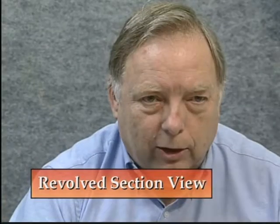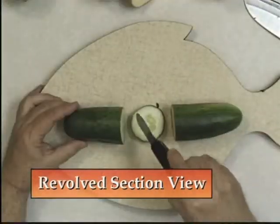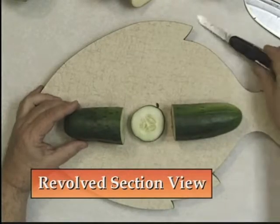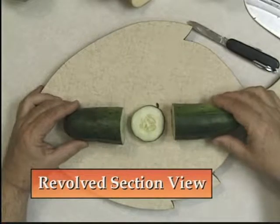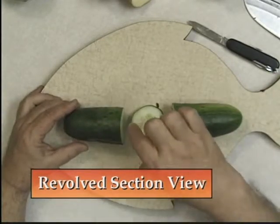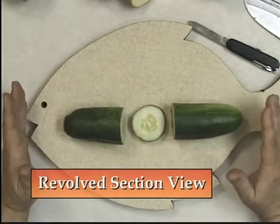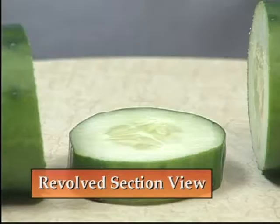You'll see later when we get to the formal views that we actually leave a little space or a little break in the view for the sectioned part. So here we have this long object and we want to show the interior, so we pretend to cut a slice and revolve it right in place, and in only one view we have incorporated a revolved section.